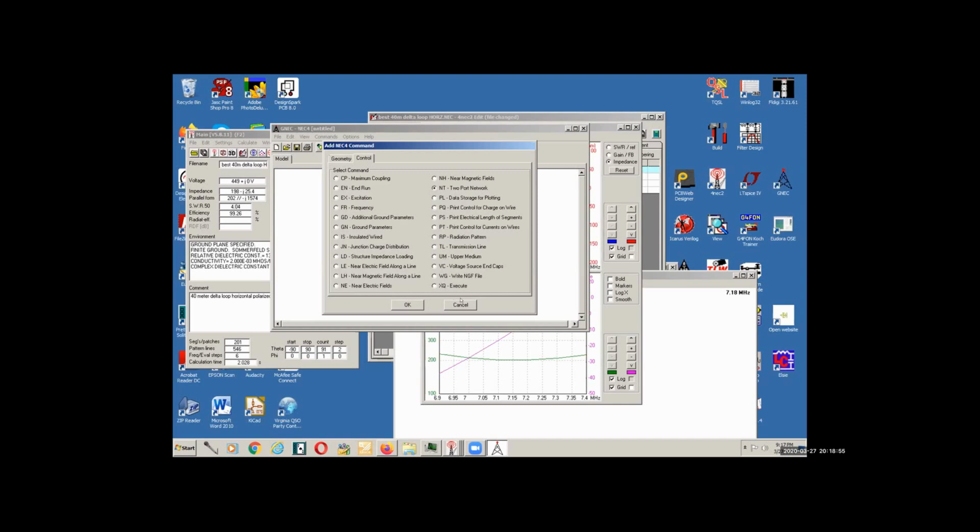And then I discovered, by the way, I ran it on 20 meters, and guess what? It works on 20 meters. A little bit higher takeoff angle, but it actually matches pretty close to 50 ohms through the balun on 20. So I can actually use this antenna, particularly for short skip on 20 meters. I can use my delta loop that was designed for 40, I found out.